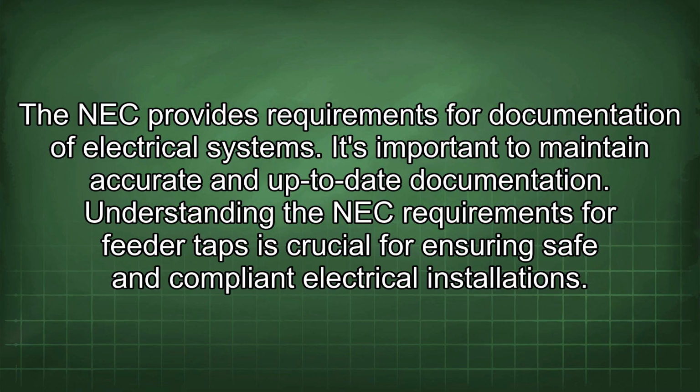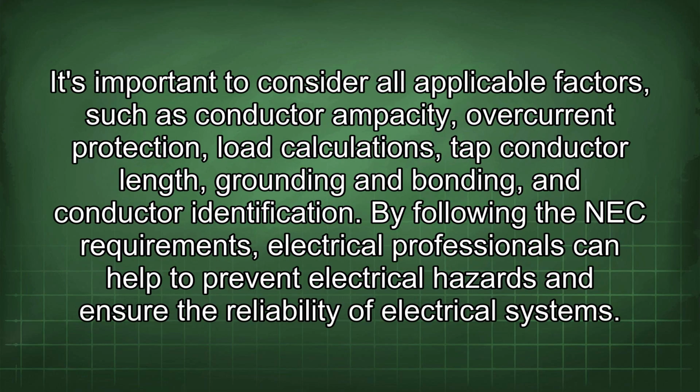Understanding the NEC requirements for feeder taps is crucial for ensuring safe and compliant electrical installations. It's important to consider all applicable factors, such as conductor ampacity, overcurrent protection, load calculations, tap conductor length, grounding and bonding, and conductor identification. By following the NEC requirements, electrical professionals can help to prevent electrical hazards and ensure the reliability of electrical systems.